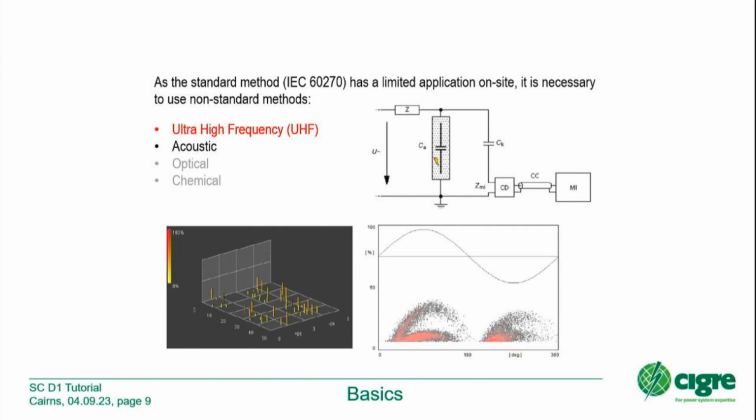Maybe the radar signals, which is typically 1.1 gigahertz, or Wi-Fi signals, mobile phone signals. Suddenly it appears that in the measuring chain, there's a low-pass filter of 700 megahertz. It's a very small thing. It is erected in 2 minutes. Nobody will notice it except the commissioning engineer for the PDM and to pass the sensitivity. At the end of the day, it's wrong, because there's a change between step 2 and step 1.